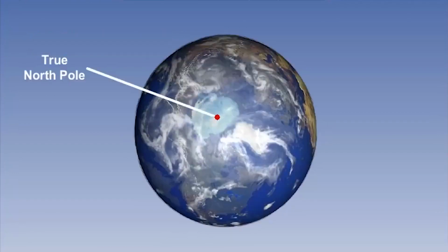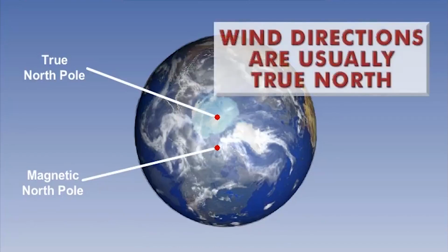However, we have a true North Pole and a magnetic North Pole. The problem is that these are not in the same geographical location. Traditional meteorology has little concern for magnetic north, and therefore wind direction is referred to true north. However, in-flight headings are referenced to the compass, which uses magnetic north. Most wind direction given by meteorologists will be referenced to true north. When using such wind directions, be careful to adjust them using the relevant variation, which allows the calculation of magnetic north.